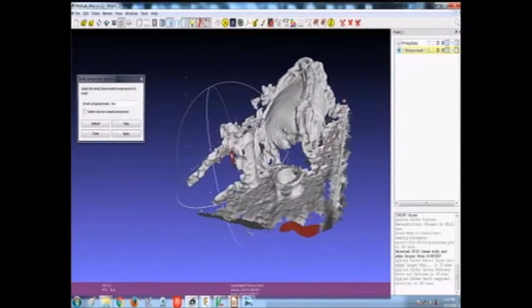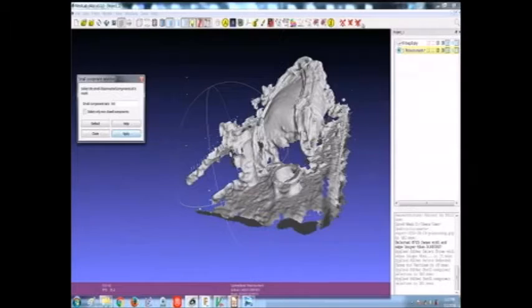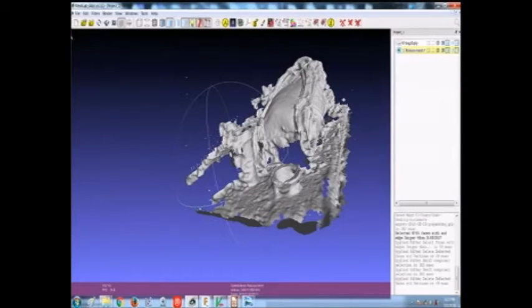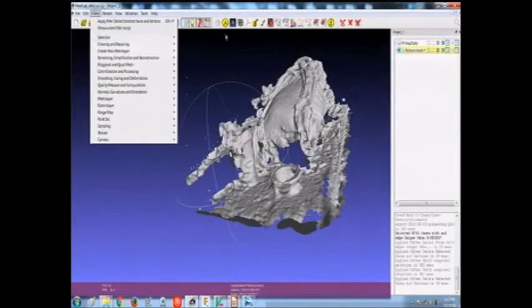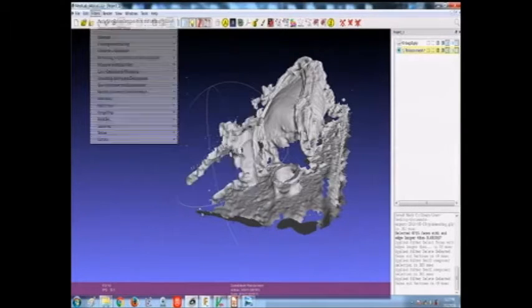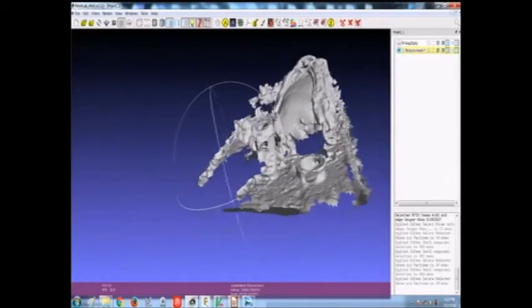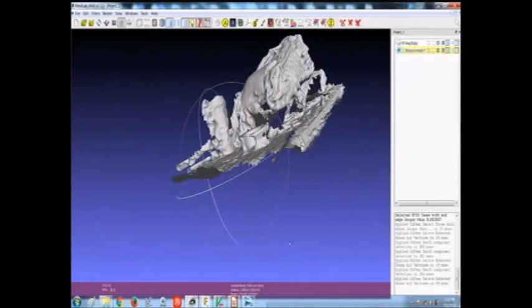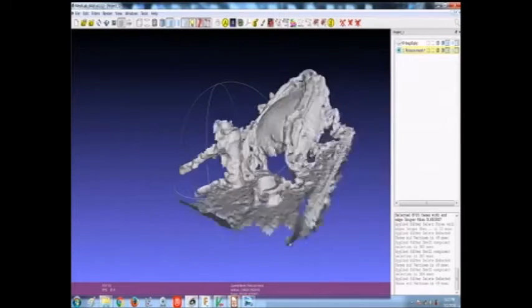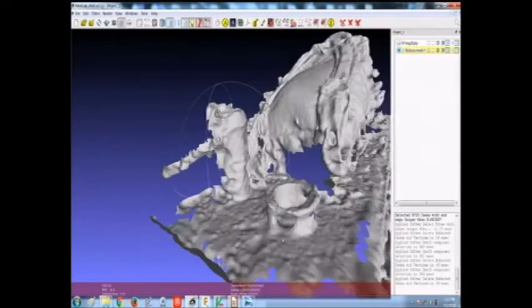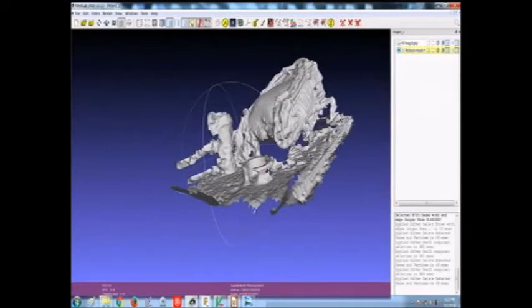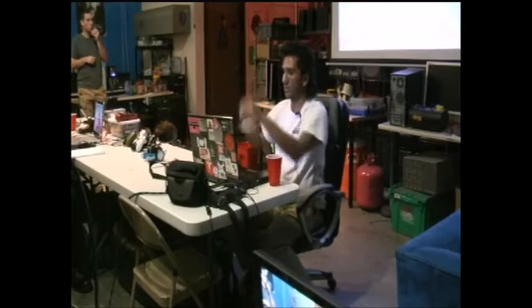We'll do this reconstruction one more time and we'll get a more refined result. So we'll go ahead and hit apply, hit delete. Oh, hold on, let me try that one more time. Third time's a charm, second time's a charm, something like that. So apply, delete. Okay, so we got rid of some dangly edges, but we still also have some rough edges, right? We want to be able to refine some of those rough edges. You can see how they're sort of spiky here. The more rounded things are, the more continuous the curves are, the better the reconstructions will be.